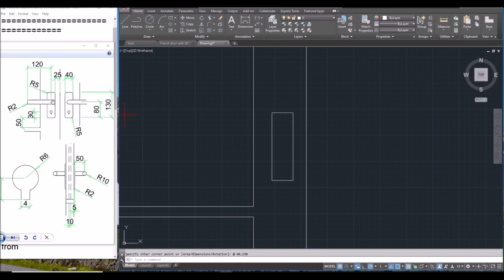So this is an arc, yeah, this is an arc, but I will draw a circle and then trim it later. So circle C, and then spacebar, and touch it and move it up. Don't click on it, just touch and move it up. Position your mouse like that. Now you can input the number directly, 80, spacebar. You can see you draw directly at that point without doing any construction line again.